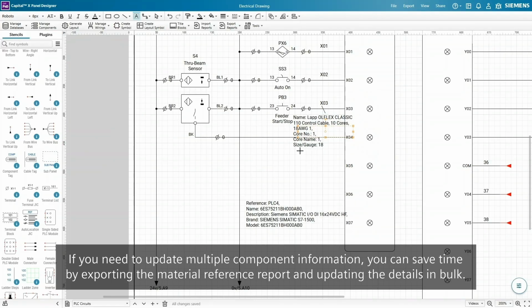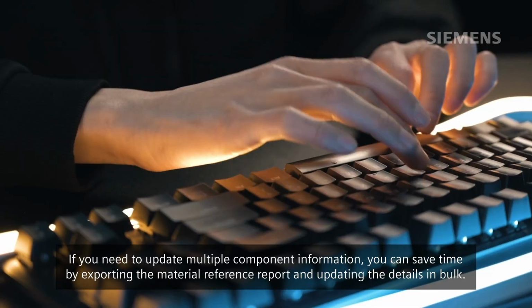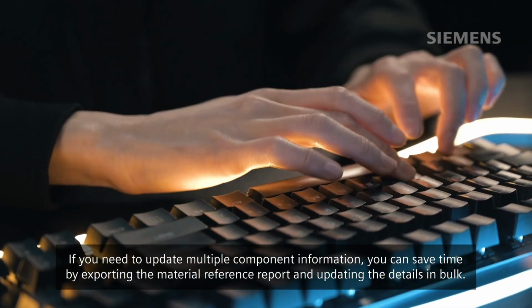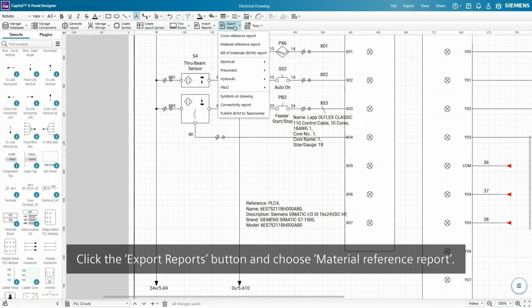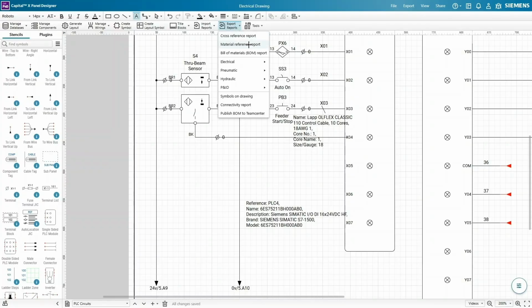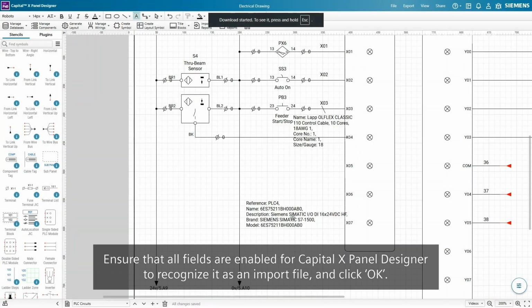Here's an extra tip. If you need to update multiple component information, you can save time by exporting the material reference report and updating the details in bulk. Click the Export Reports button and choose Material Reference Report. Ensure that all fields are enabled for X Panel Designer to recognize it as an import file and click OK.